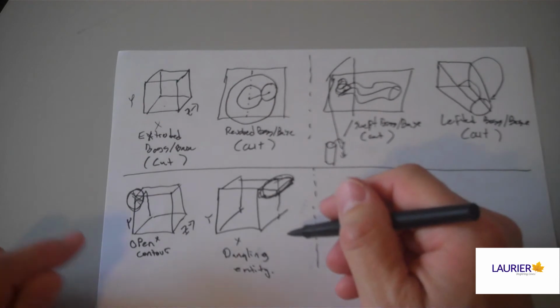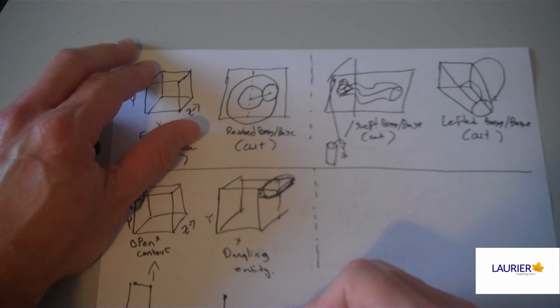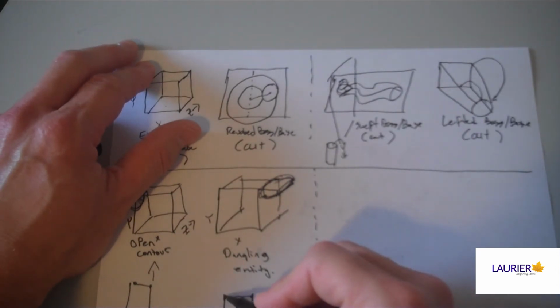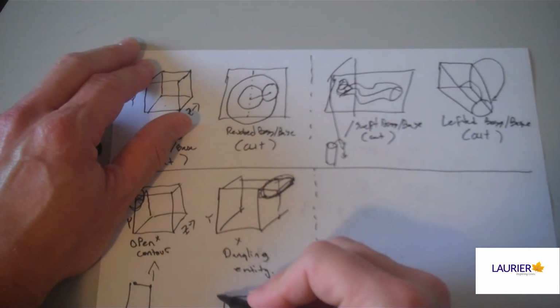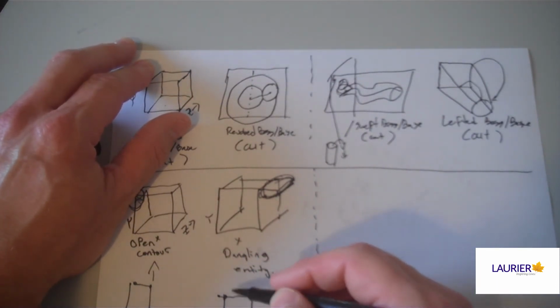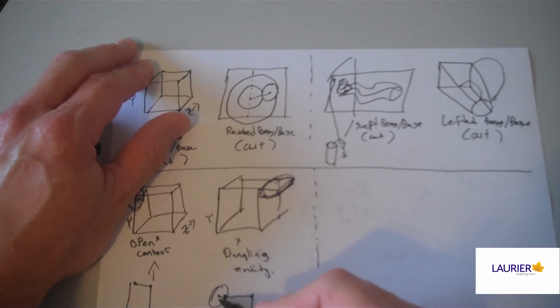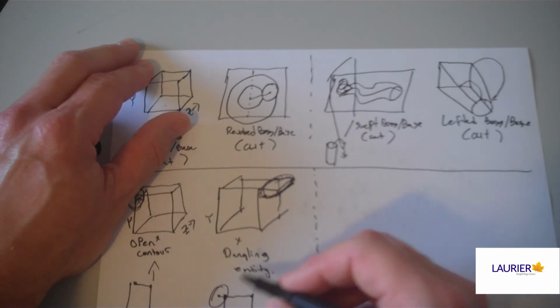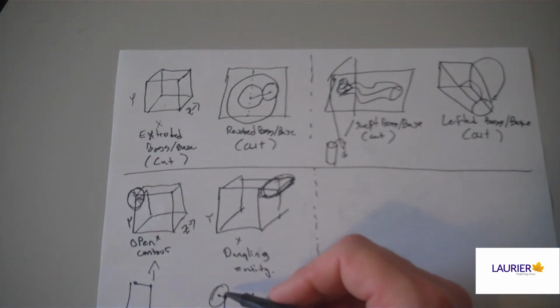We call this the click-happy error because it tends to come up when, like the open contour error, people are manually setting up a contour shape. But in this case, instead of missing the connection to the last point, they double-click to end their line instead of single-clicking. This immediately starts another line. The person then clicks again to stop drawing this and thinks everything is fine. But they've managed to leave a little tiny line hanging off the end of their drawing. This line could be 1/100th of a millimeter long, but if it's there, you're not going to get a proper extrusion. So, when you get the dangling entity error, it's probably from overclicking. To find the problem, look for a little extra line that's not part of any closed 2D contour.